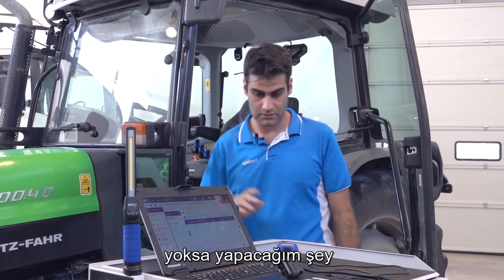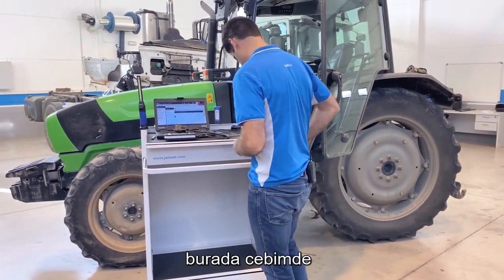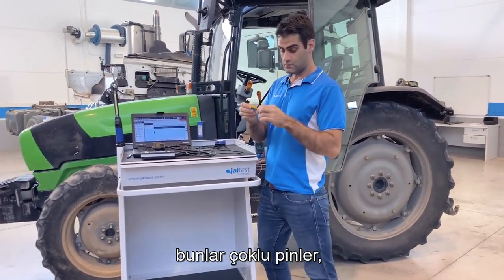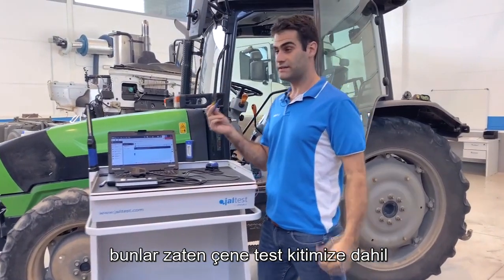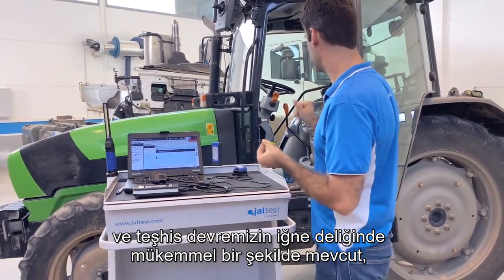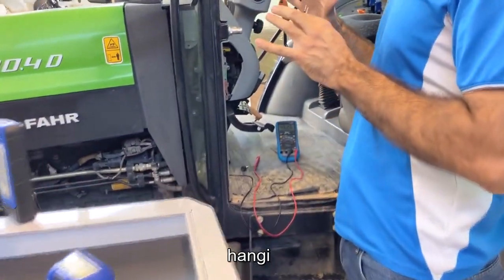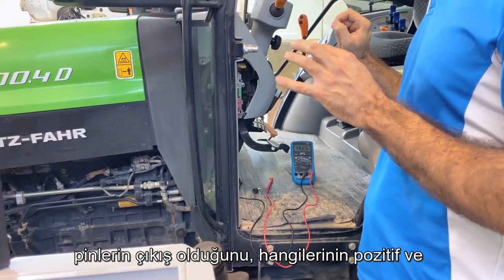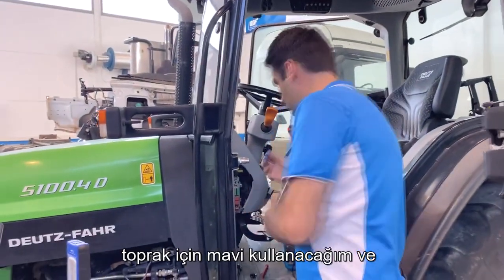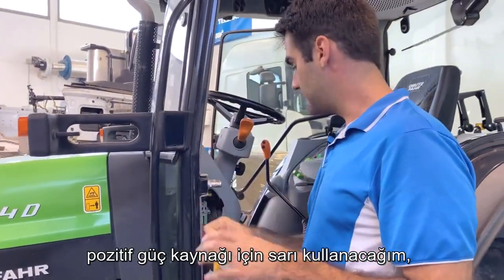If not, what I'm going to do is here in my pocket, those are multi-pins. They are already included in our Jaltest kit and suit perfectly in the pinhole of our diagnostic socket. So the first thing is to figure out which are the pin out, which are the positive and the negative of our OBD socket. I'm going to use blue for ground, and I'm going to use the yellow for the positive power supply.